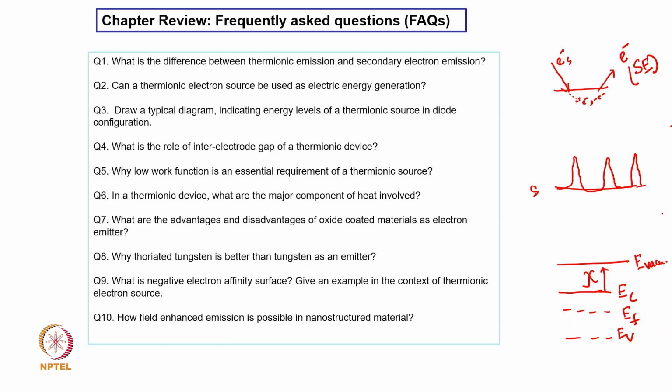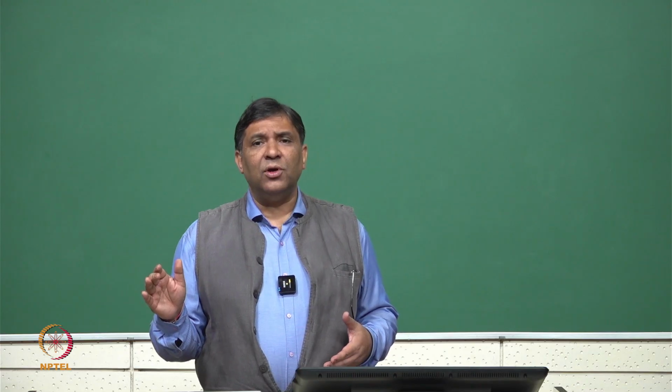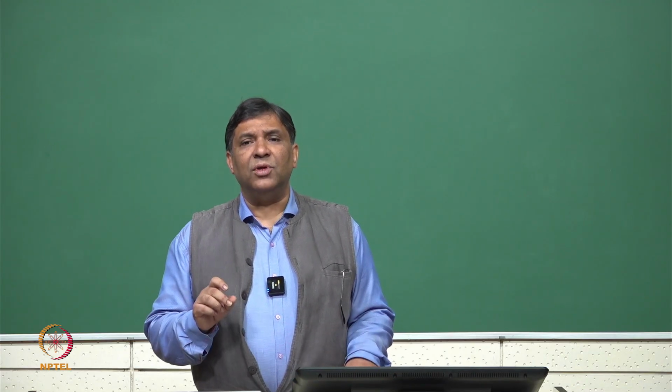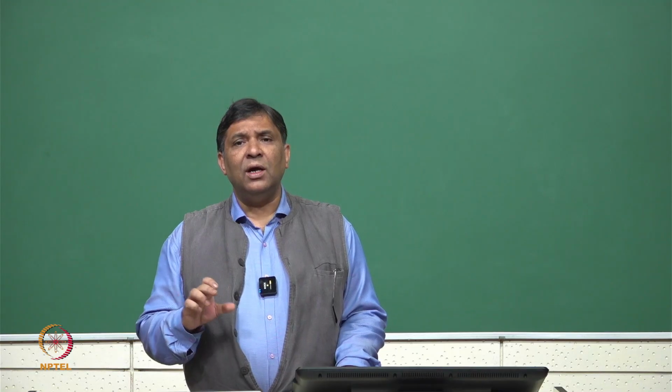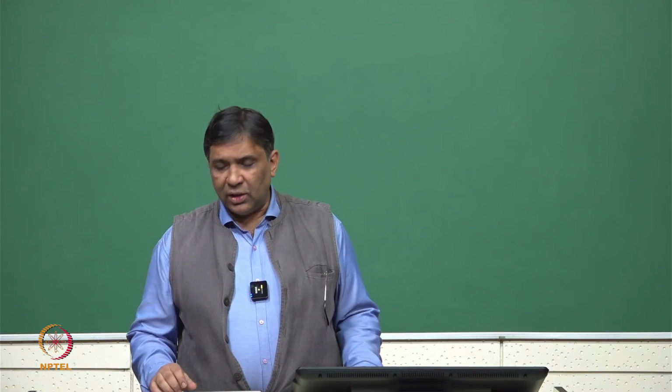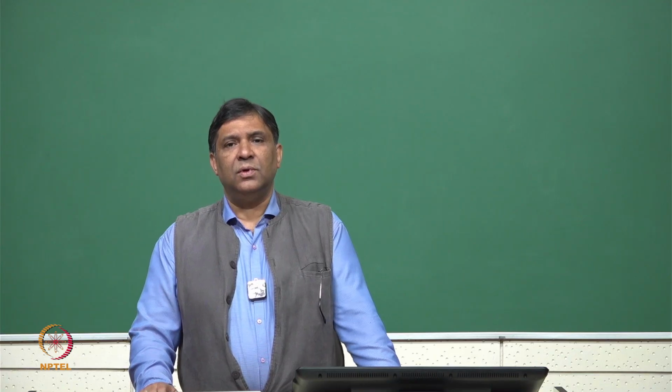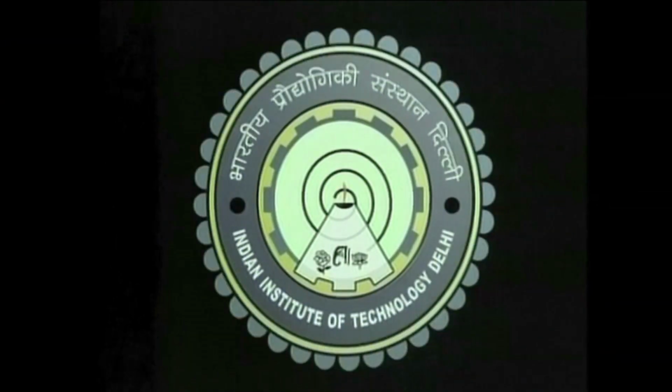We use a sharp nanostructured material, and then we can also have a low work function coating. That will enhance the electric field as well as the emission probability. Because of low work function, we have higher probability of electron emission, and because of the sharp nature of the emitter, we have higher electric field, and it can give more electrons due to the field emission process.